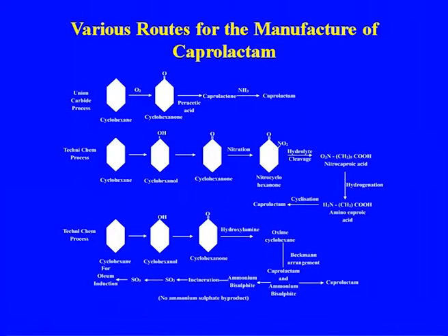This is the cyclohexane process where we get cyclohexanol, which is converted to cyclohexanone, and then the Technichem process, again a cyclohexane process that we are using. Finally, during the oxime cyclohexane Beckmann rearrangement we get the caprolactam, and during the process we also generate, as I told you, ammonium sulfate.